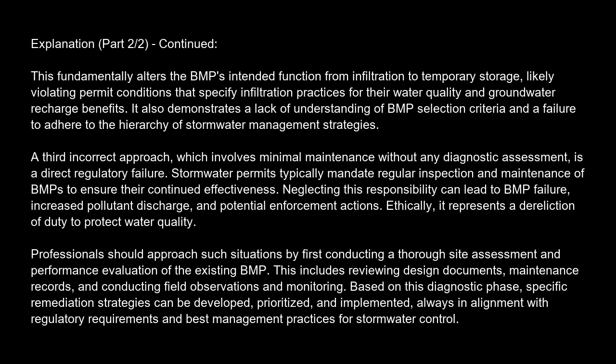stormwater management strategies. A third incorrect approach, which involves minimal maintenance without any diagnostic assessment, is a direct regulatory failure. Stormwater permits typically mandate regular inspection and maintenance of BMPs to ensure their continued effectiveness. Neglecting this responsibility can lead to BMP failure, increased pollutant discharge, and potential enforcement actions. Ethically, it represents a dereliction of duty to protect water quality.